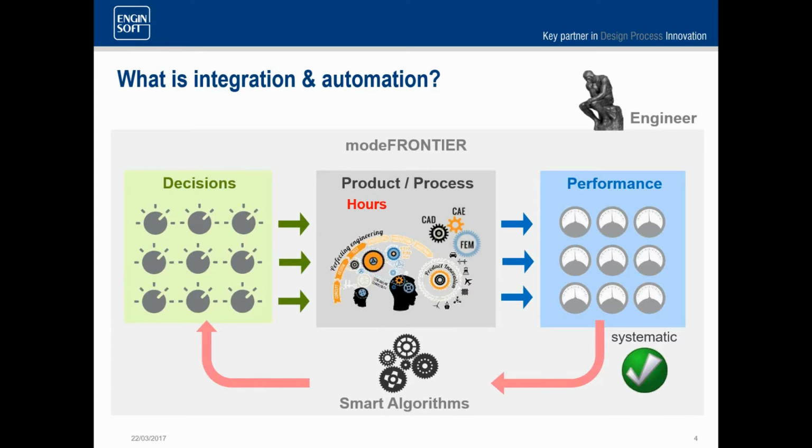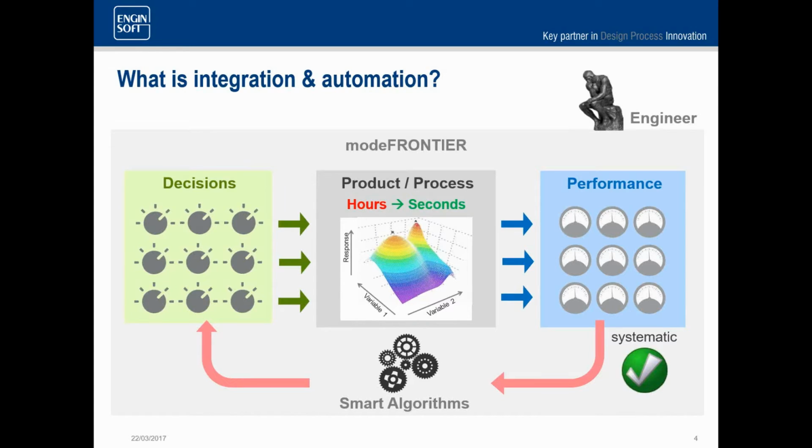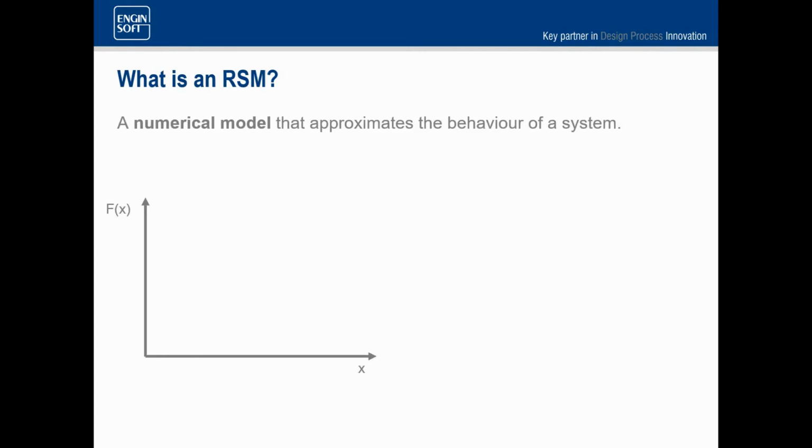Certain algorithms may not be suitable for this kind of optimization just because of time. So we're going to look at surrogate models or response surfaces, how we can replace part of this process by just sampling a part of the design space and training these response surfaces. We can then run an algorithm over the top to view the design space and find the optimal in seconds rather than in hours, and really reduce the time that we're taking to do this kind of work.